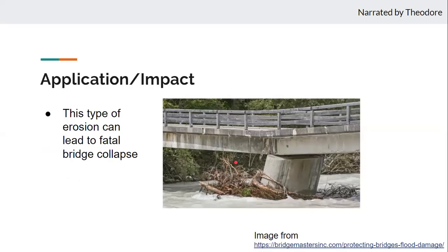This is a clear example of how scouring caused structural failure for a bridge. These types of mistakes are sometimes related to engineers not considering significant storms that may happen once every 50 to 100 years. The larger volumes of water moving through the river will cause deeper scouring and remove the foundation of the piers. Larger flow rates would require deeper foundations in order to support a given bridge.